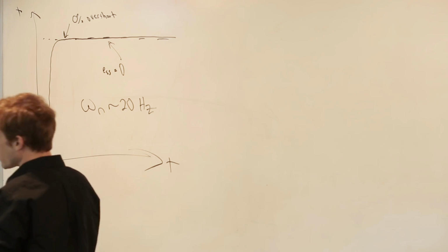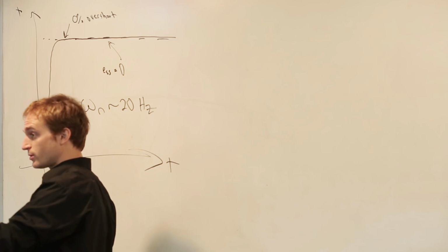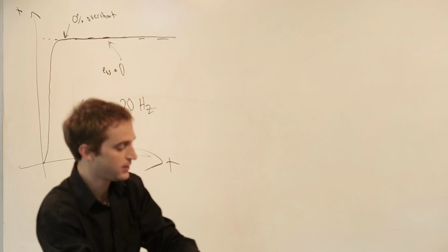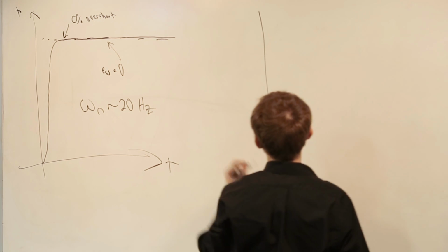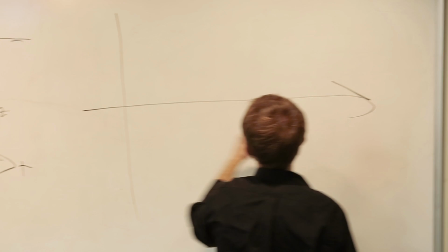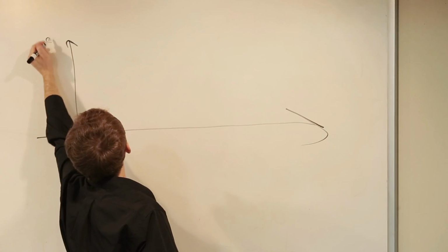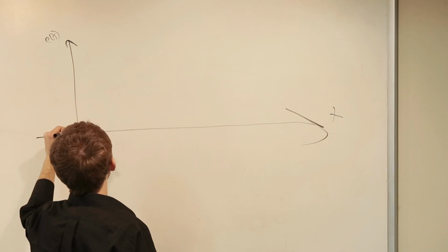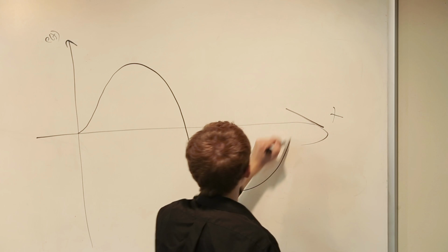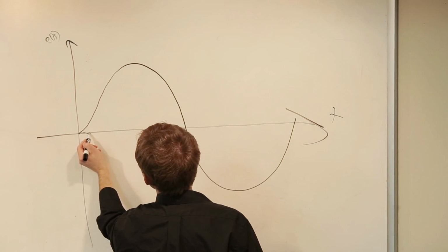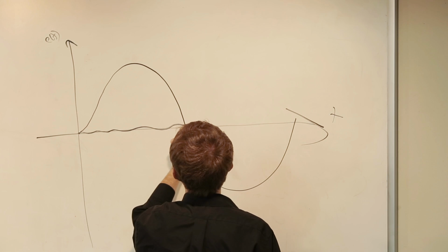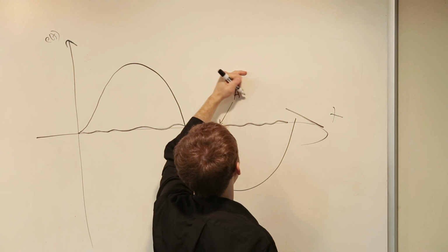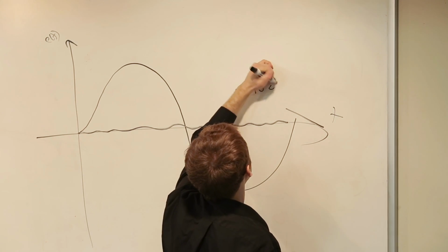You'll probably get better performance from motors 2 and 3, the brushless motors, just because brushless motors are generally way better than brush motors. And then for your parabolic velocity move, if you have this commanded velocity, you should try to just have a following error that is centered around 0 with an amplitude less than 10 counts.